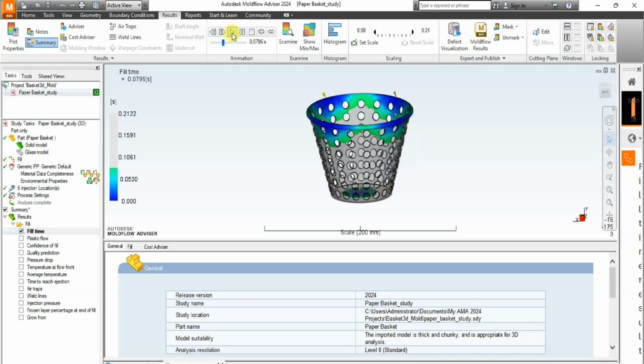Okay, the fill time. So let's talk about hesitation. What is hesitation? This is the filling of the thick section first, because of the less resistance to flow, which can of course cause a short shot, the one we previously explained. So hesitation has to do with the attribute of a simulation filling the thick parts and leaving out the thin edges. I'm focusing on the thick parts.